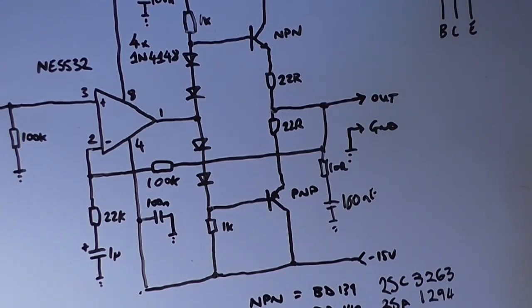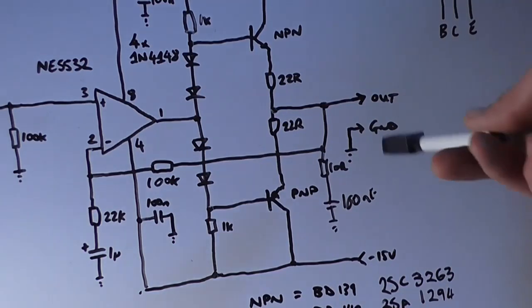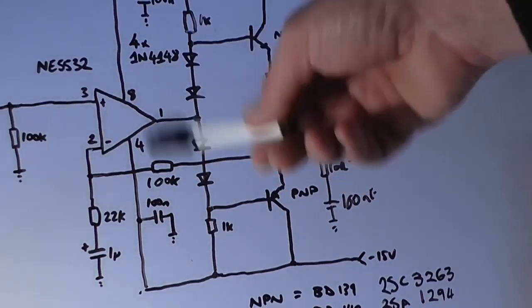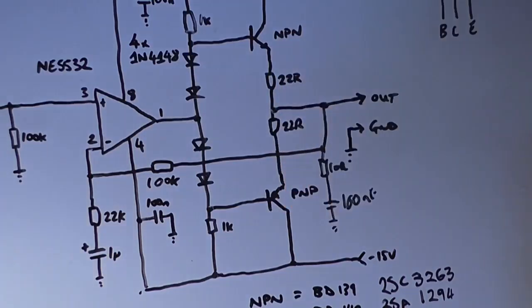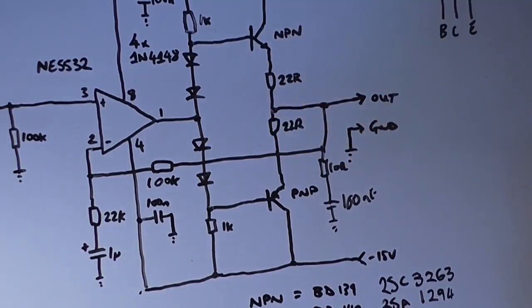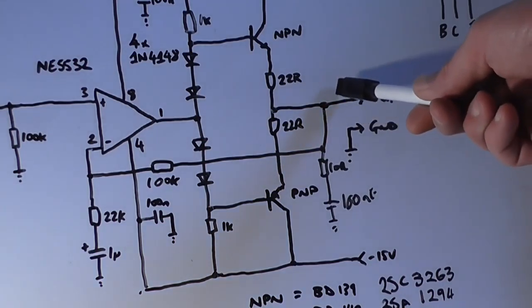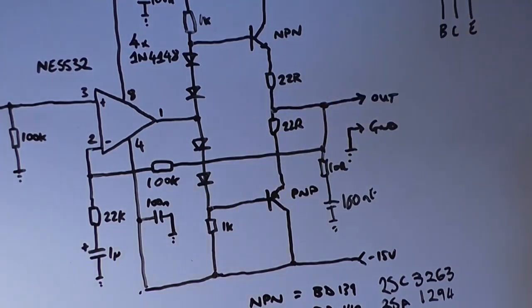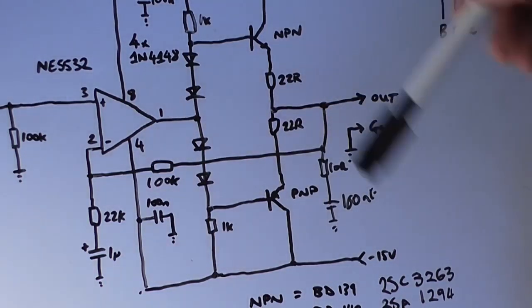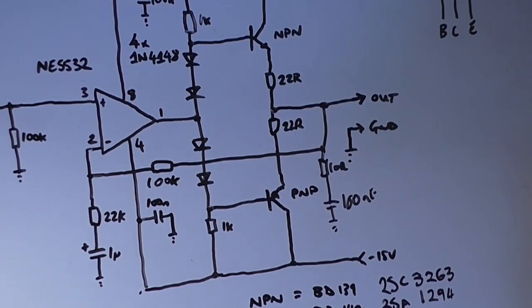That will help prevent the amplifier stage here from going into ultrasonic oscillation, which will start heating up output device transistors very quickly. You could also add a small coil and another 10 ohm resistor in parallel with each other on the output leads, which will help if you're driving capacitive loads, such as a loudspeaker on long speaker leads.